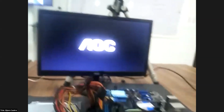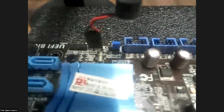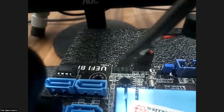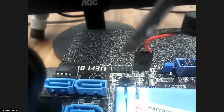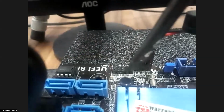So let's turn this on now. So it's already have power. How can we turn on a motherboard that has no power button? So actually, this is where your power buttons are here, connected. So meron siyang parang ganito, saksakan ilalagay dyan. But since we don't have that, what we will do is to short circuit that pin. Okay? From there, it's now alive.